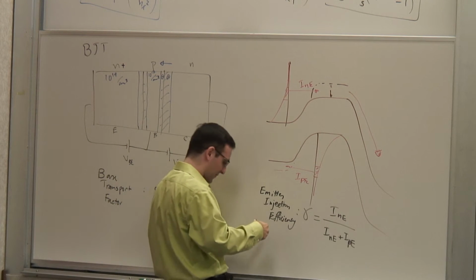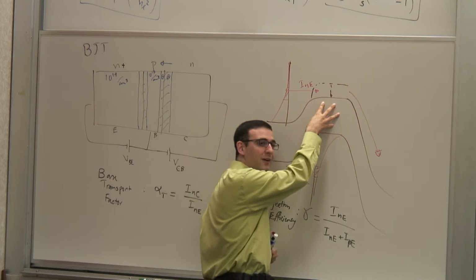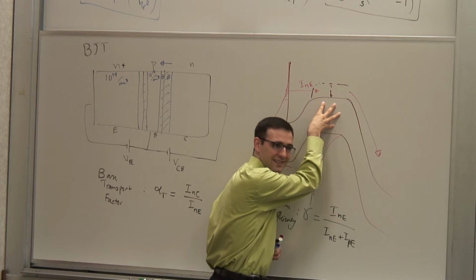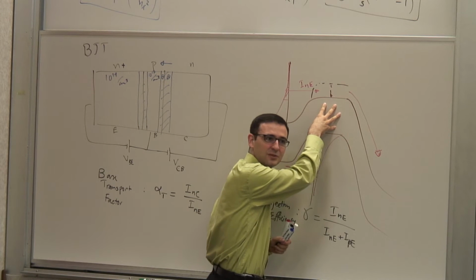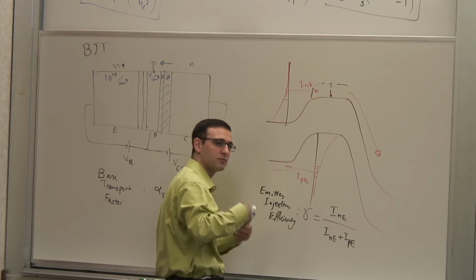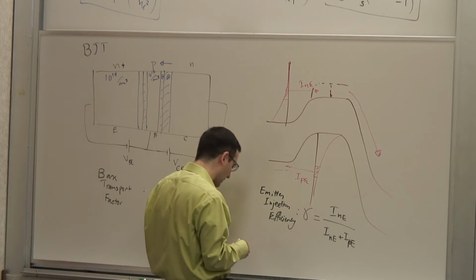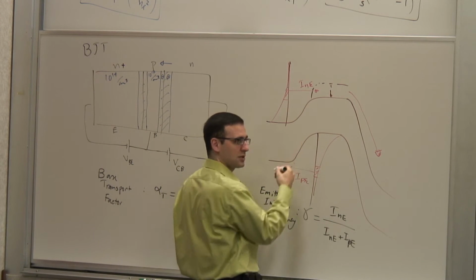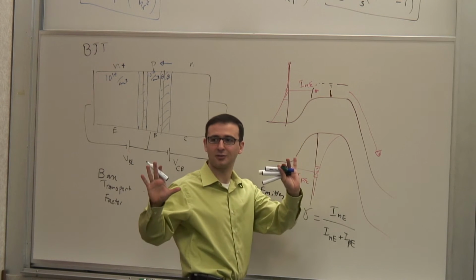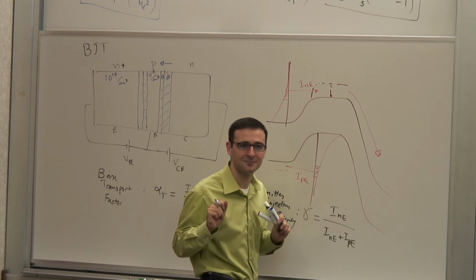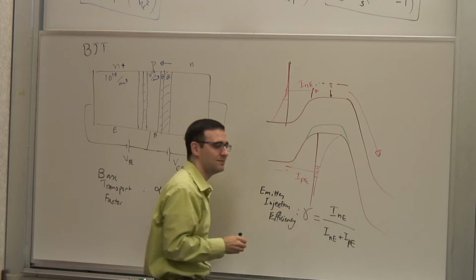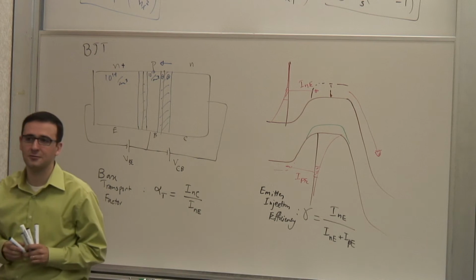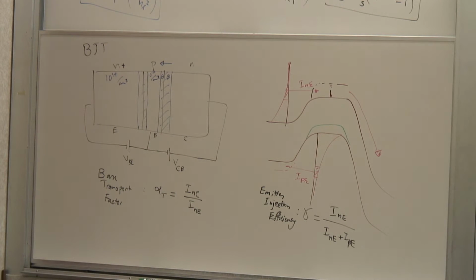We do it this way usually. What we do, we modify the material at the base. So the material at the base has a smaller band gap, which has the same effect as what you just suggested, but from a practical standpoint, that's what we often do. So what if I could make the base material somehow, let's say magically, like kind of engineer the band gap, so it has a smaller band gap, like that, just in the base. What would happen in that case?